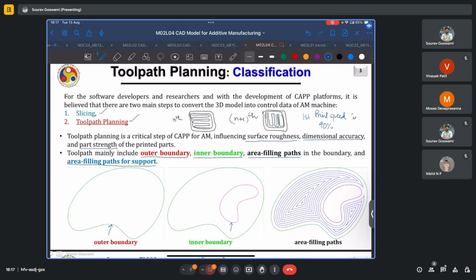That is, you have these paths which are almost following the contour boundary, and then you keep offsetting them towards the center, and you end up with these patterns. Of course, you'll find that based on the complexity of the geometry or the bead spacing, the bead thickness, you might end up with areas which can have pores, like one here.